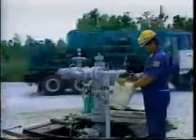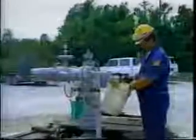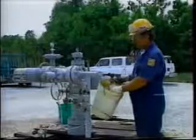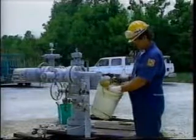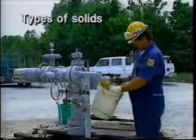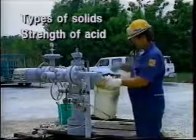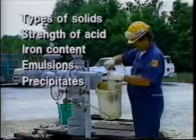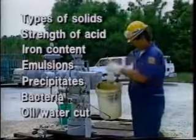It is important to catch samples of the produced treating fluid after the job. Samples should be obtained periodically until approximately 500% of the treating volume is recovered. The fluid should be tested for types of solids, including amounts and sizes, the strength of the acid, iron content, emulsions, precipitates, bacteria, and approximate oil-water cut.